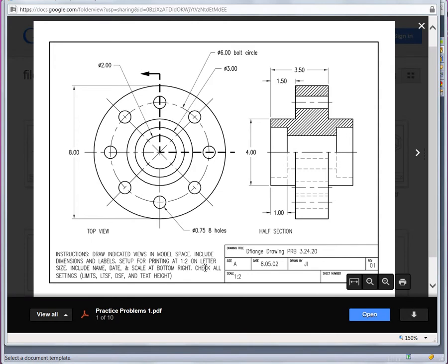Alright, we're going to take a look at developing the D flange drawing here, the model, which is really a collection of mirrored sketch entities revolved to create a feature. And in addition, we've got a pattern of holes here. So if we were to study the drawing for a moment, we can see that this is going to be our top view. And noticing the symmetry here, we can determine that using the section that's provided, we can actually turn the sketch on its side and develop it in the right profile.